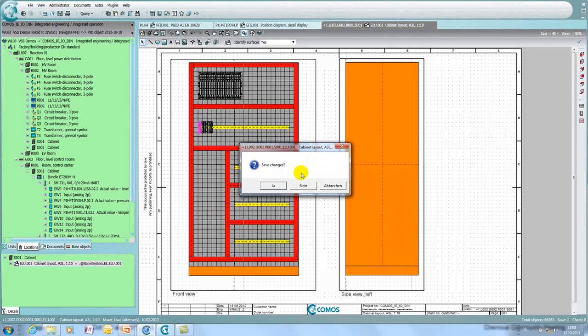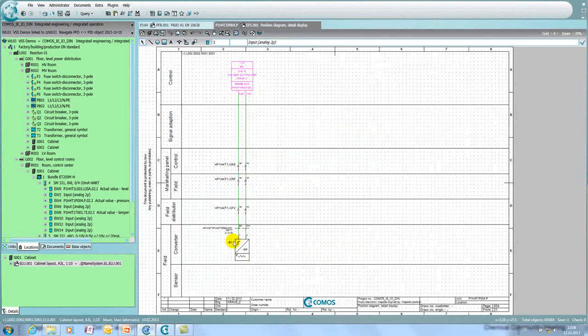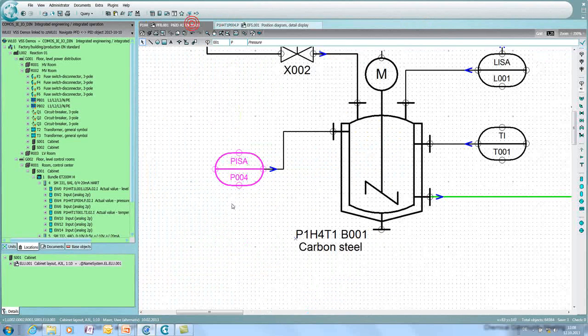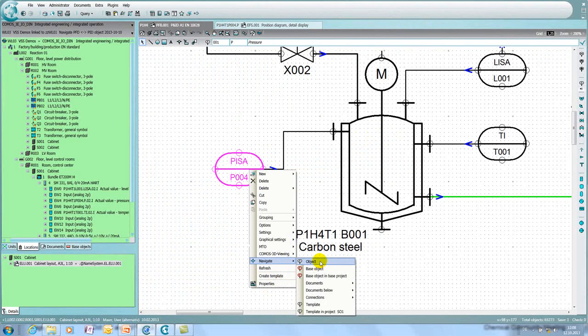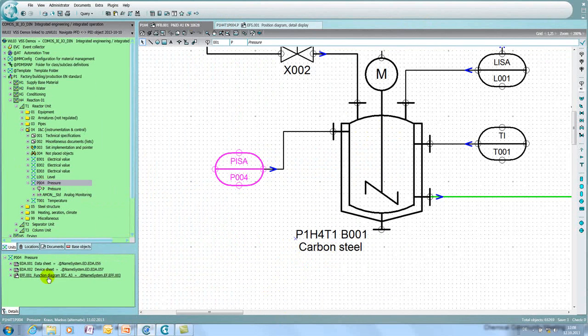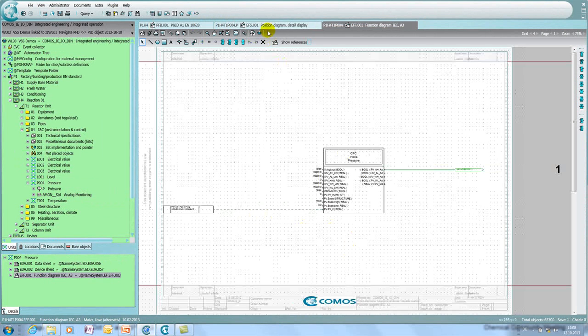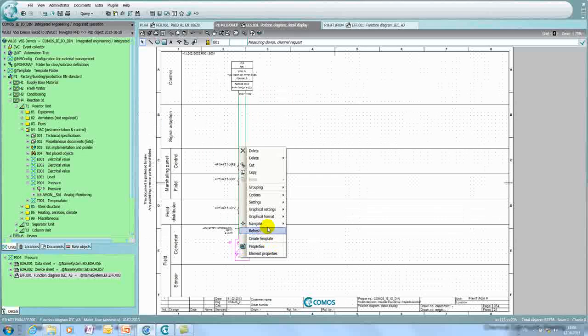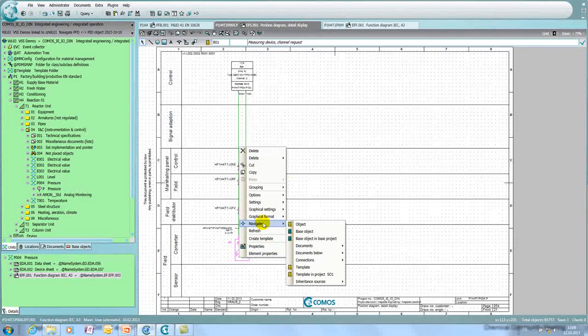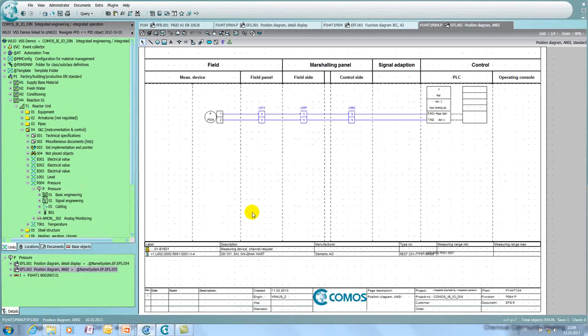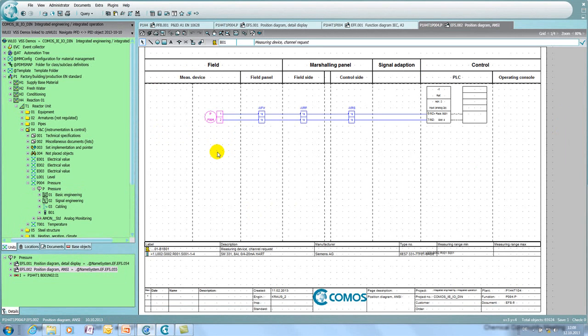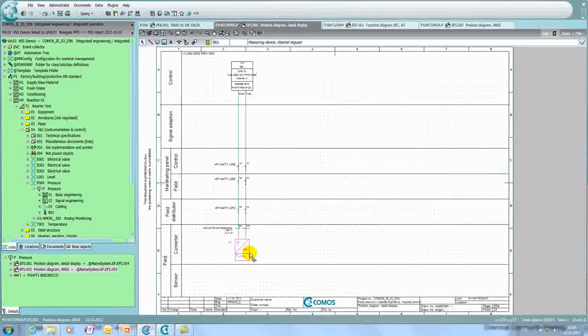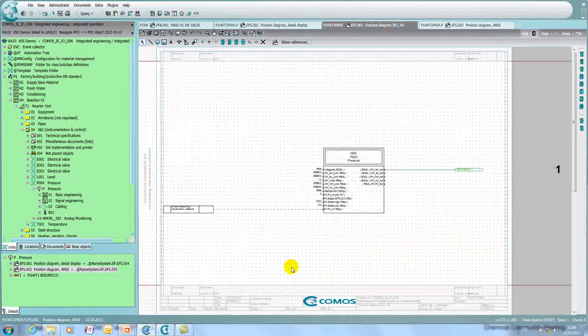We also can proceed without changing. We can now proceed to the pressure function once more. We navigate to the object, and when we look into the pressure, we see the function diagram. In parallel, when we look at the position diagram here, this is our German or European appearance. We also have the documents available for ANSI standards, and this shows us exactly the same stuff. If we replace that item from a 2-wire to a 3-wire, the symbol would be affected in both of these drawings here. Let's proceed with the function diagram.